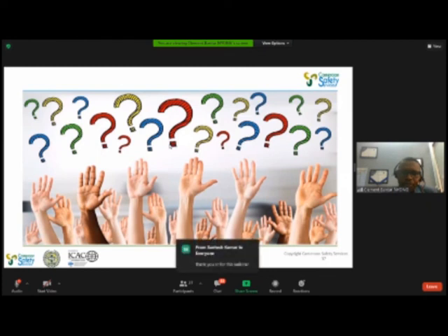Okay, I have a question: what was the main reason for the Deepwater Horizon disaster in the Gulf of Mexico? Actually, I don't have access to the official report, but from documentation, during drilling there was a blowout, if I'm not mistaken, and there was a cement job which was done in order to isolate this undesirable event, but the cement job was not properly done.